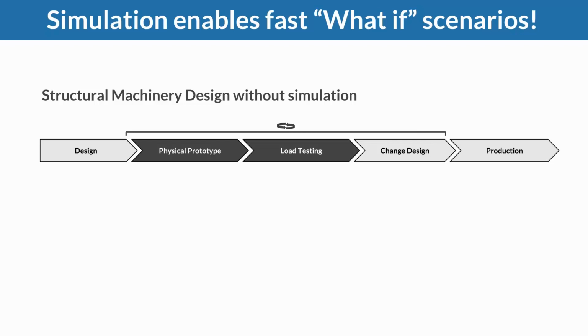Sometimes you basically fail to measure at the right locations, so you would have to redo the test, put your measurement points in different locations where they make more sense, where you have the extreme, like the failures, for example, where cracking appears, where the highest deformations appear. And then based on your measurements, you can make some informed design decisions where you iterate once more with an updated design and build a new prototype.